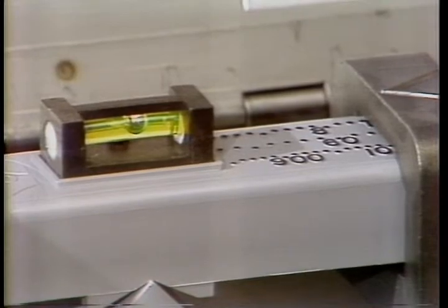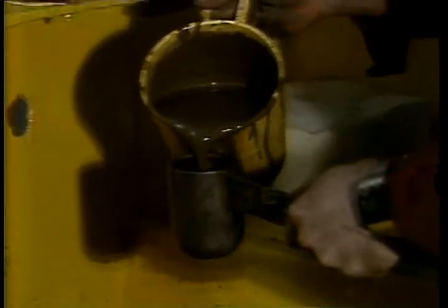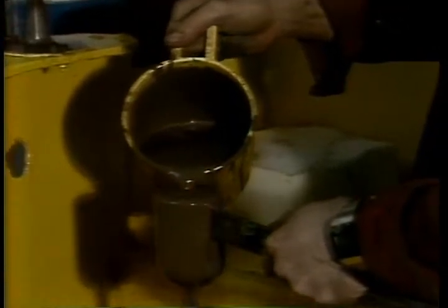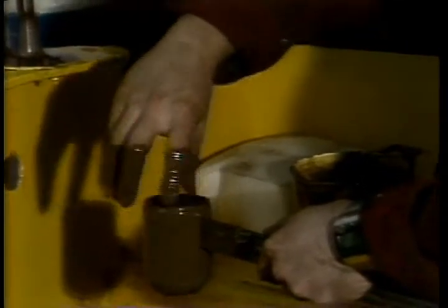Maybe we'd better go over that procedure too. Take a mud sample from the return tank. Be sure that for each reading, your sample comes from the same place. Fill the cup to overflowing. Dip the lid into the mud sample and spin it onto the cup. This seats it to make sure all air is out of the cup. Cover up the hole in the lid and rinse the mud off of the cup.